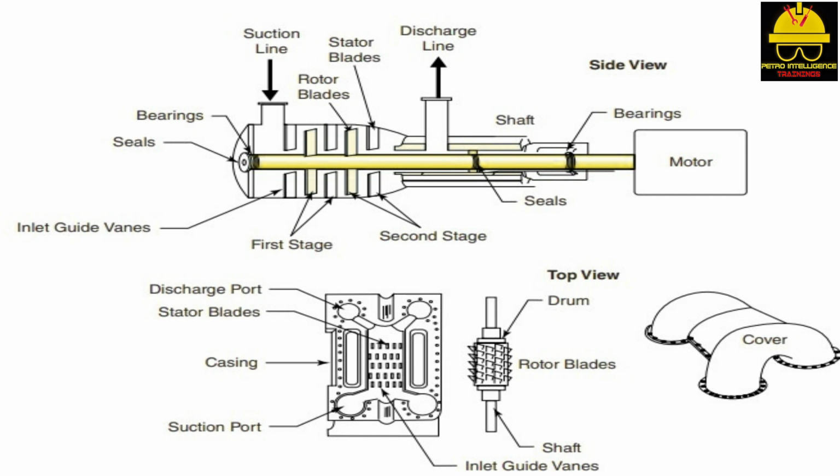The stator blades in an axial compressor can be fixed, individually adjustable, or continually variable. Individually adjustable stator blades can be adjusted from outside the casing. Continually variable blades are adjusted by a drive ring linked to a drive shaft that is automatically actuated by a power cylinder. In contrast to a centrifugal compressor, axial compressors accelerate and compress gas in a horizontal, straight-through motion, without the turbulent changes in direction characterized by centrifugal compressors.